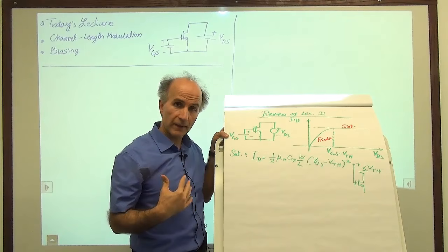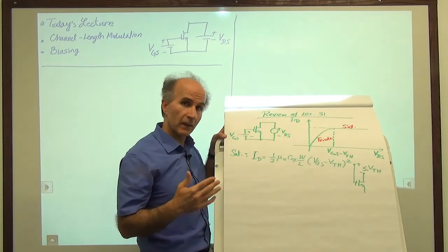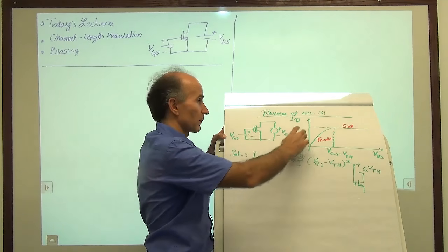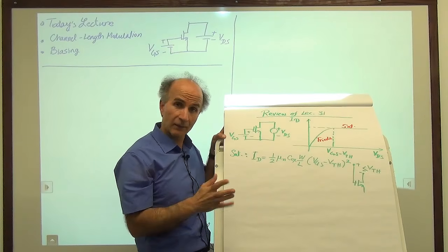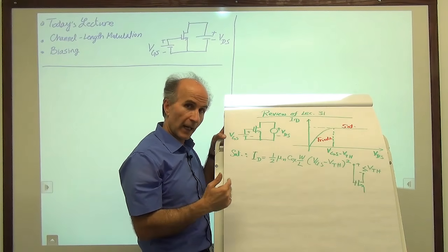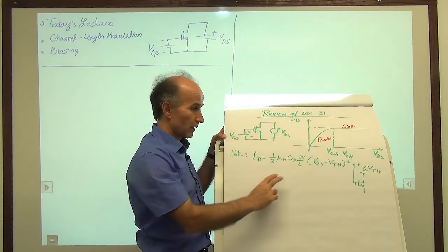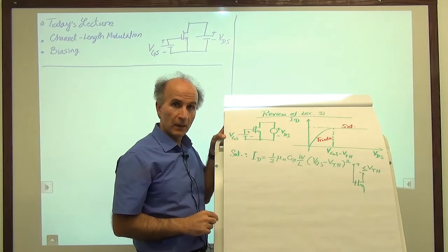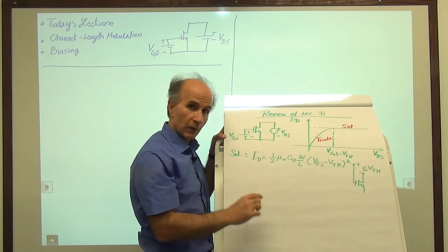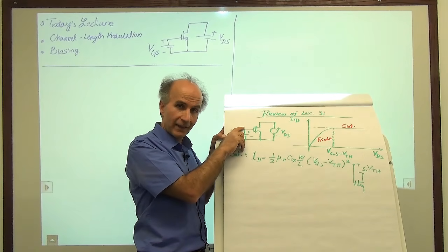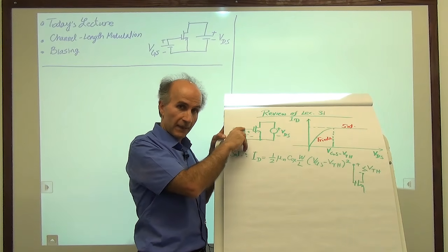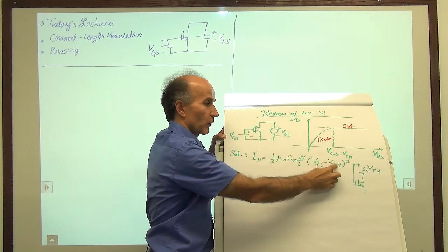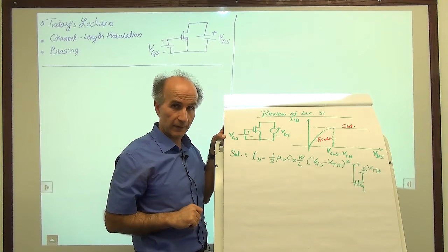So in our circuits in this course, we are mostly interested in MOS devices operating in saturation. In saturation, we say the current is constant, maybe relatively constant, as we will see shortly, as VDS changes, but it's a function of VGS. And it's a quadratic function of VGS. So if VGS is equal to VTH, meaning at one threshold, the device is right at the edge of off or on. And then as VGS exceeds the threshold, in proportion to the square of the overdrive, the current increases.